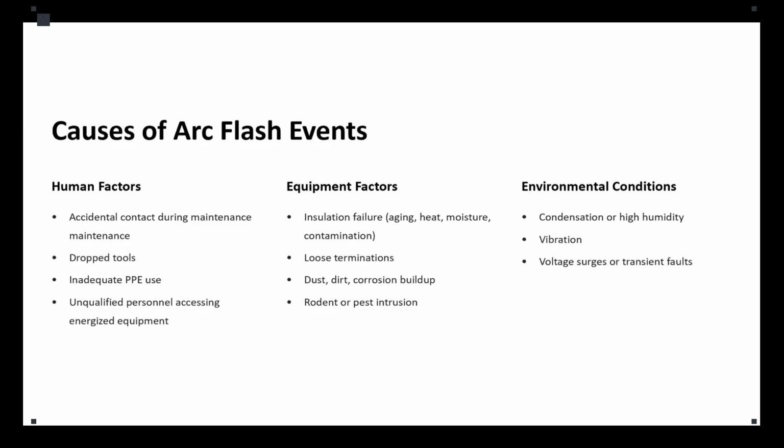If you look at the experimental test results for that standard, you can see that a slightly loose connector significantly increases the temperature rise under nominal operating conditions in that equipment.